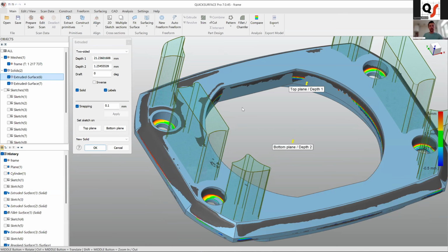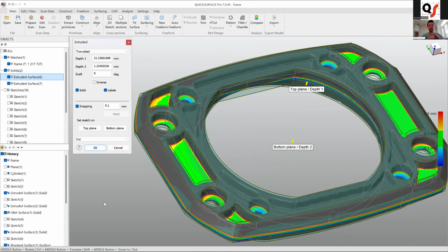Sorry to interrupt you here. When we speak about this tolerance that you use, 0.1, 0.05, we've been on the market for many years, and my advice to all of you is don't get too low. If you put 0.01, which is 10 microns, you'll never get the perfect result. So be realistic. Normally, with these types of scanners, a good expectation is something between 20 to 50 microns. Victors is using 0.1 because of the type of the project. 0.1 is good enough. But if you want to be extreme, our recommendation, Victors, is what, 30 to 50 microns, I guess, something like this.